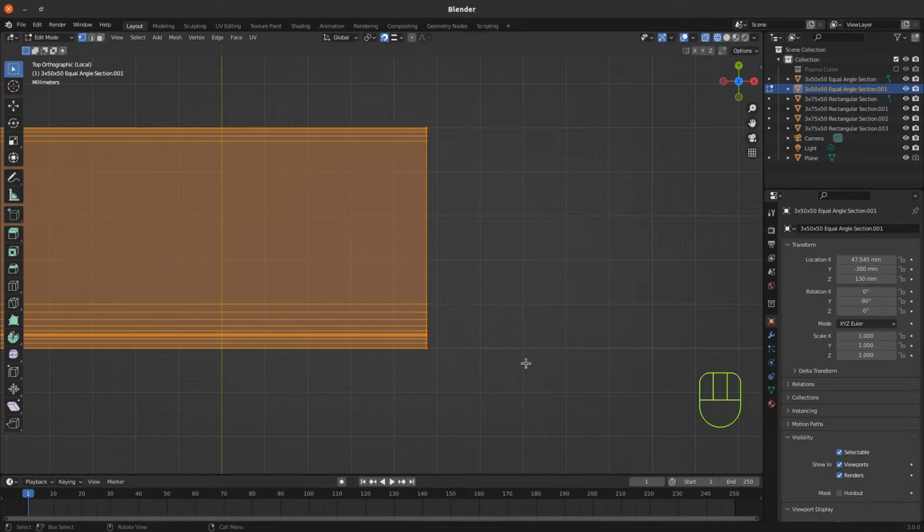So I'll start off first of all by pressing K to open the knife tool, and you'll see across the bottom of the screen the list of the different commands that are now used with the knife. Cut through, which used to be Z, is now C, and angle constraint is A.